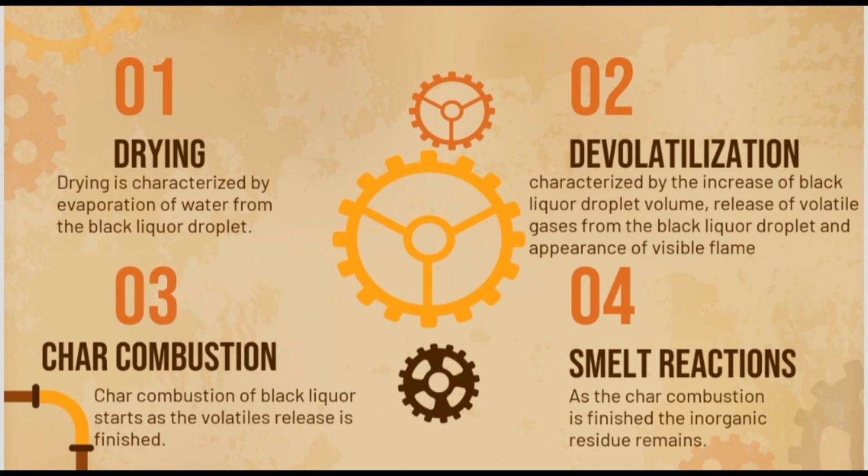Hydrogen, carbon monoxide, carbon dioxide, light hydrocarbons, tar, and sulfur-containing gases have been reported to be the main products during devolatilization. Devolatilization is characterized by the increase of black liquor droplet volume, release of volatile gases from the black liquor droplet, and appearance of visible flame. The last one is the most typical criterion for determining the length of the devolatilization time in experimental droplet combustion studies.